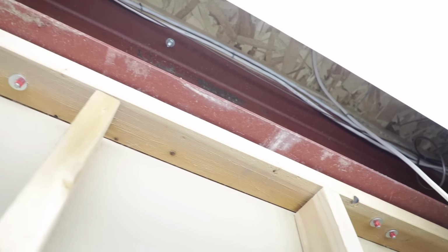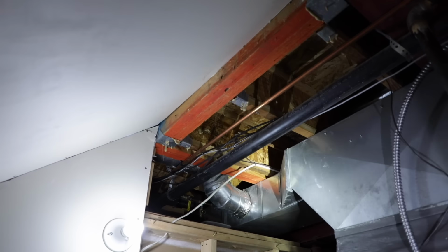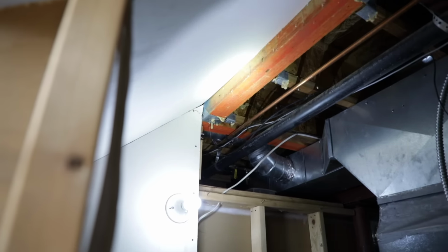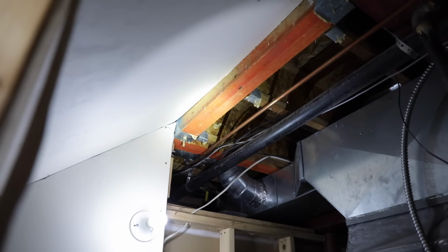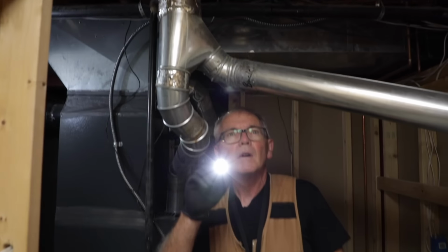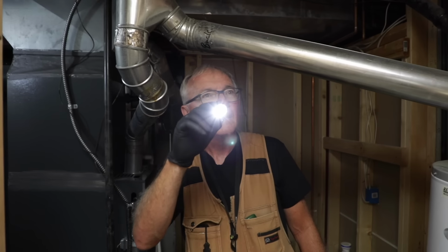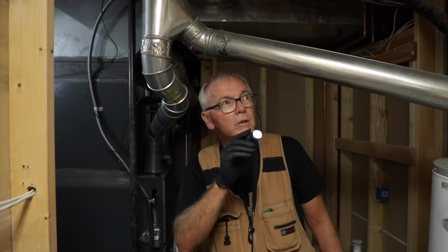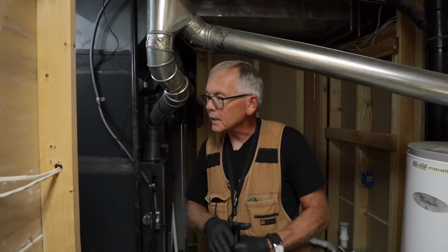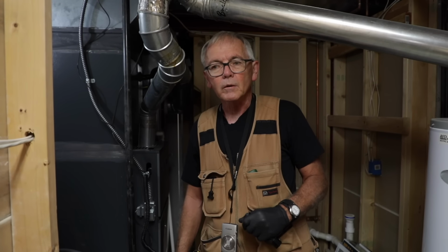We also have a steel I-beam, which is part of the main support. And back here, we've got a microlam beam right at the top of the stairs. This is carrying the weight of the stairway at the top. Everything looks pretty good. I'm not seeing any issues whatsoever, any twisting or sagging. But again, we're just in a very small area where we can review this kind of material. The rest of the basement's 95% finished, so we're going to have to exclude that in the report.